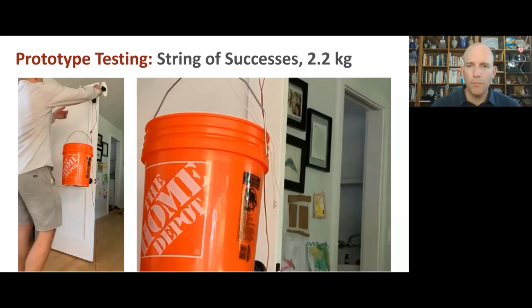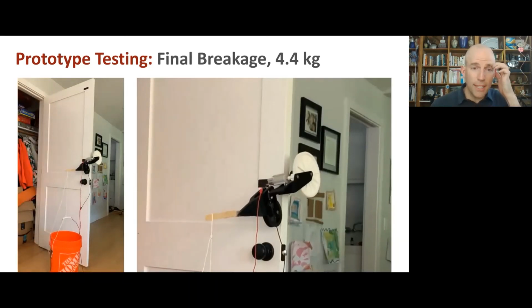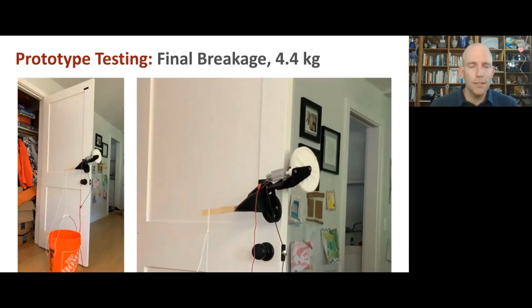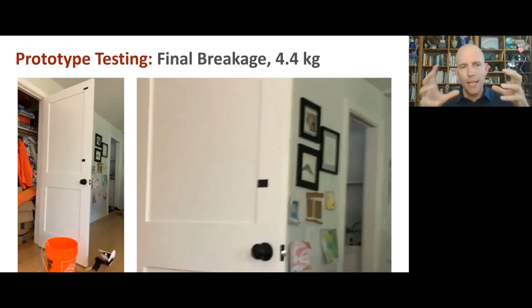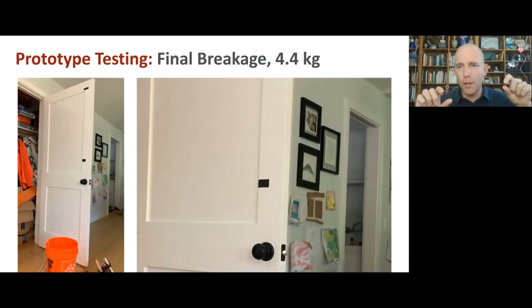But the failure mode that we ran into was that as we tried to increase it, that nonlinearity and the apparent friction coefficient caused it to slip and slip, and had to make that lever bigger and bigger, and eventually couldn't climb the wall. This was with 4.5 kilograms, and during that fall there, the wheel, the big gear smacked the ground and sent a shock into the little gear, and the little gear broke.